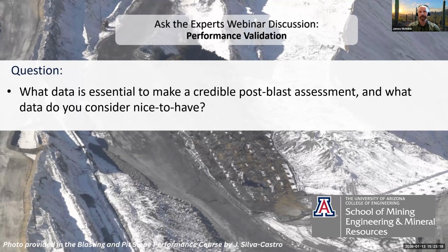One of the things that seems to not get recorded a lot of the time is what the rock critical PPV numbers are, because they help to tell us how the fracturing is going to propagate through the rock at the wall. And then you need the design vibration levels that are predicted at the wall from your models.